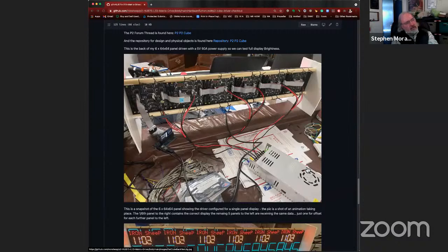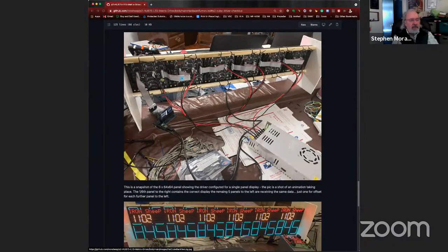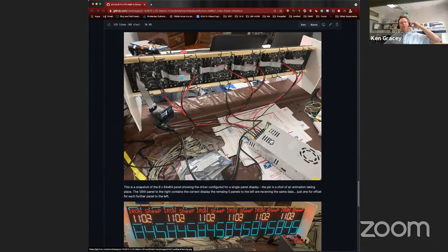When they're doing the text display that you see below, they're only drawing 0.3 of an amp per panel. But when I do full white, all the LEDs turned on with no PWM, they will consume about 8 amps per panel. I have each pair of panels driven by 1 set of wires. So you've got 3 sets of wires, and essentially each set of wires is doing 20 amps max. I only need 16. Wow. So that's how we're doing that.